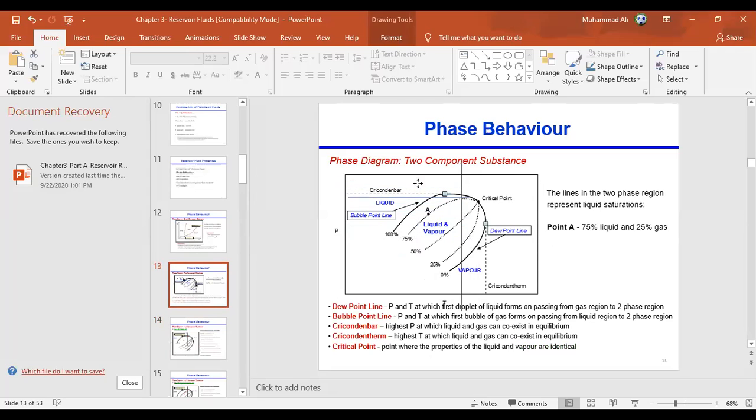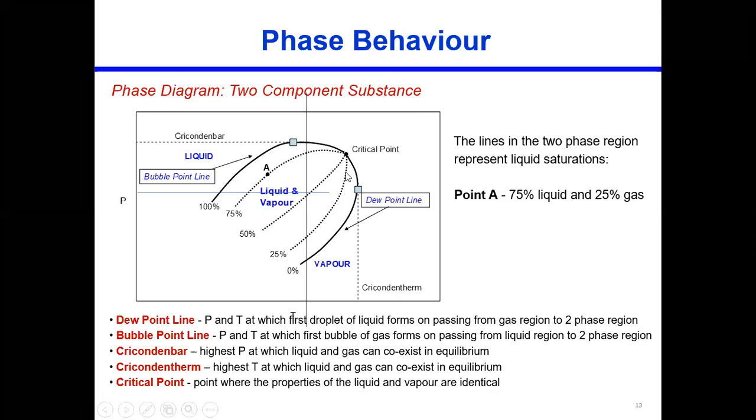So we basically play with both lines, temperature and pressure. As the life of the reservoir is progressing, the pressure especially is changing. Temperature probably remains the same, but the pressure is changing a lot. So this line tells us what kind of reservoir we are dealing with. And by matching these two points here, for example, we can tell how much oil and how much gas we currently have in the reservoir. These are the two things that we need to learn.